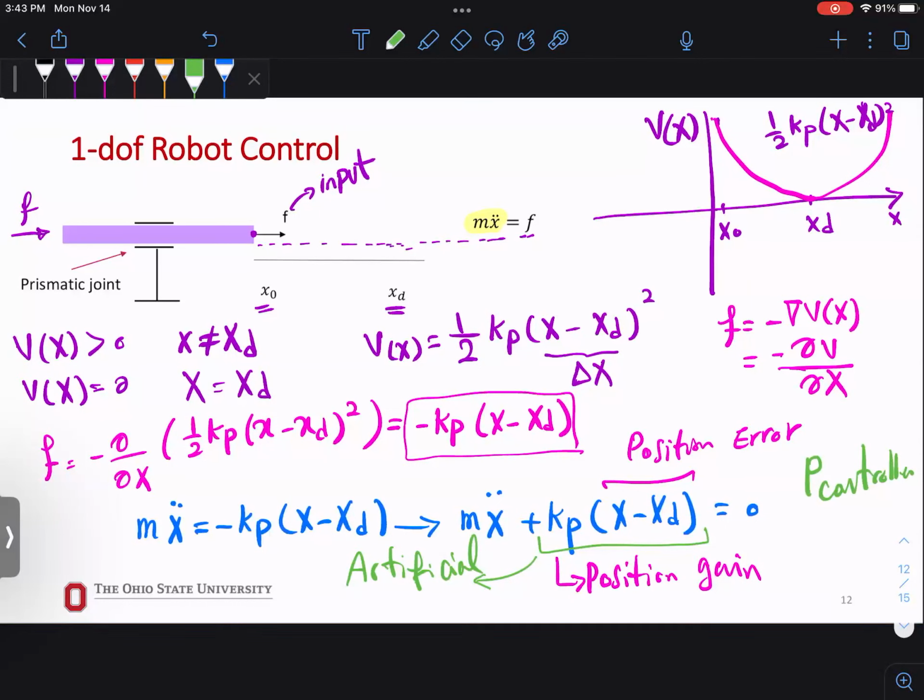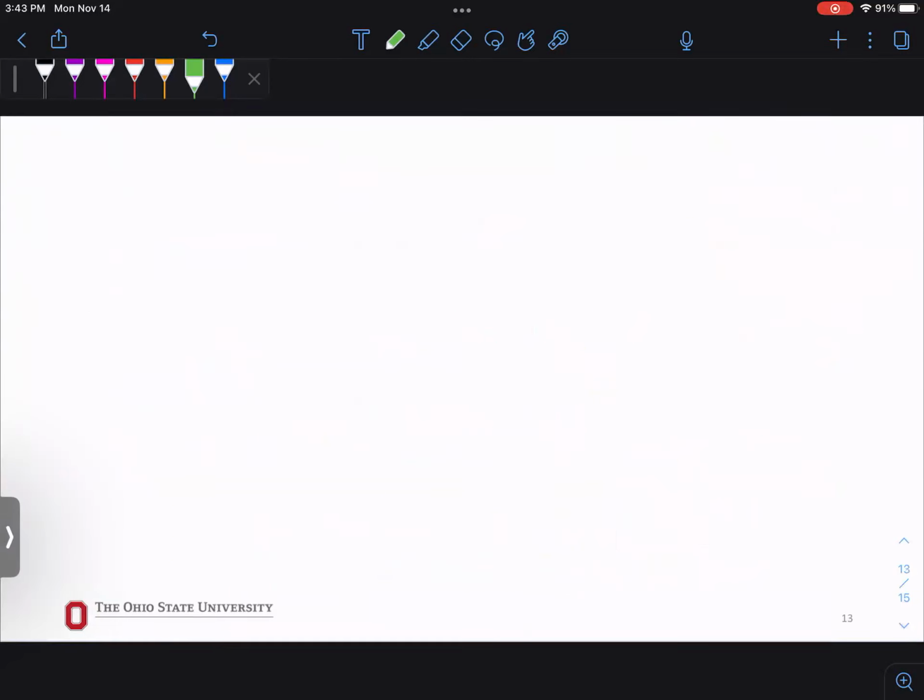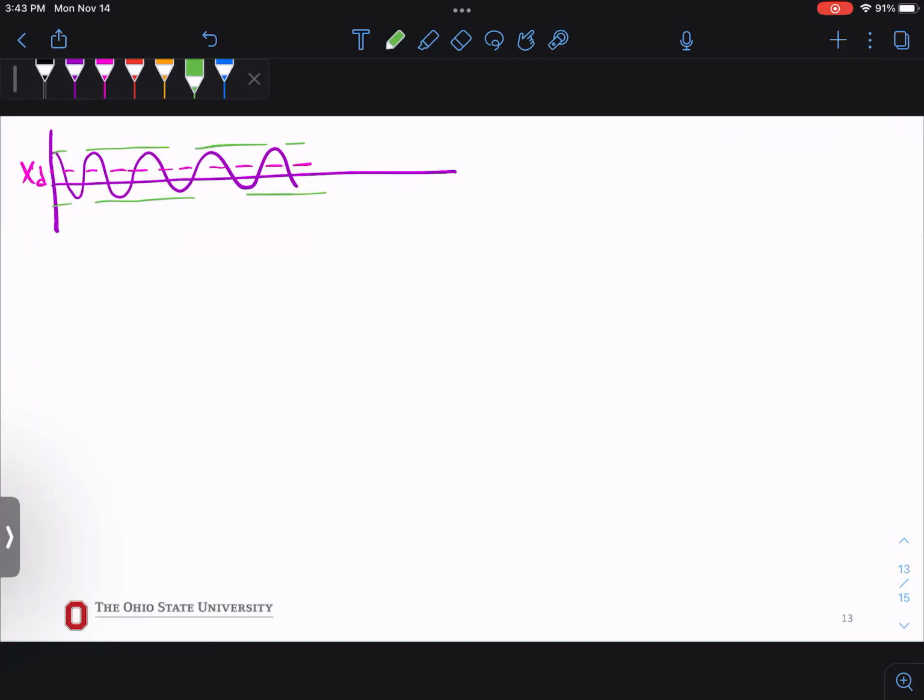Now, as you saw, we are not sure what's going to happen, since we are not stopping our system, so we're not stopping the F. We could go from some position to, let's say, if this was our x desired, we keep oscillating about that x desired because we keep crossing it and trying to come back, crossing it, changing the KP, going back and forth.